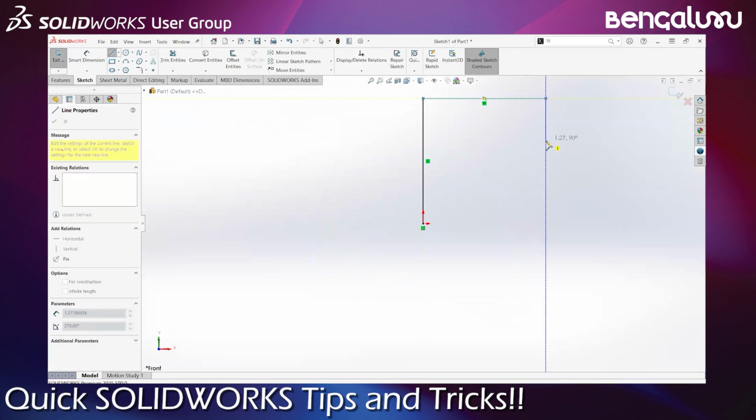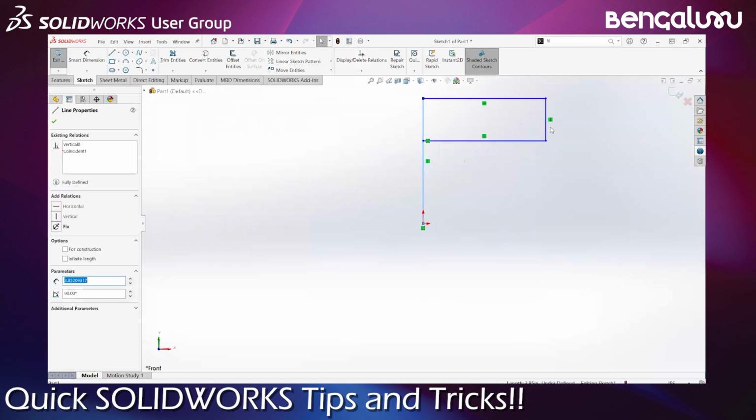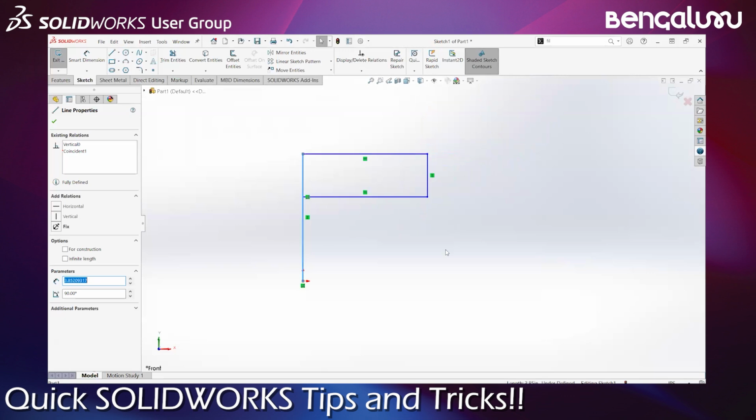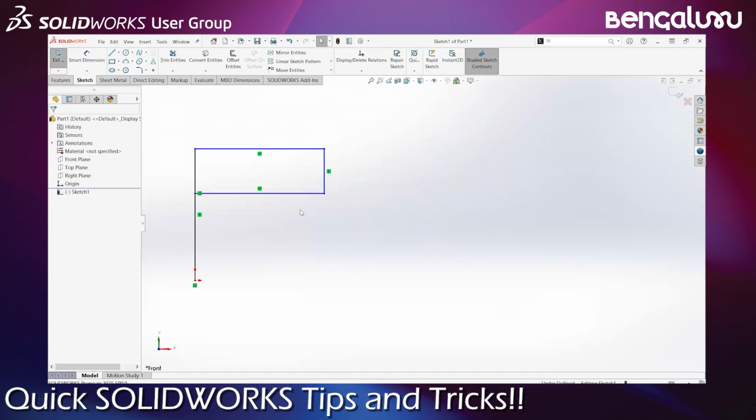So you can see that when I'm drawing lines, I just created a few sketches here. You can see that we are automatically adding these relationships or constraints, right? So the geometry constraints, I would say. So the coincidence, the horizontal and vertical, right? There are cases where you would still want that option to be on, where you want SolidWorks to add all these relations. But especially when you're in the new product design cycle, where you yourself don't know the relations yet, you are still figuring out what the relations should be.